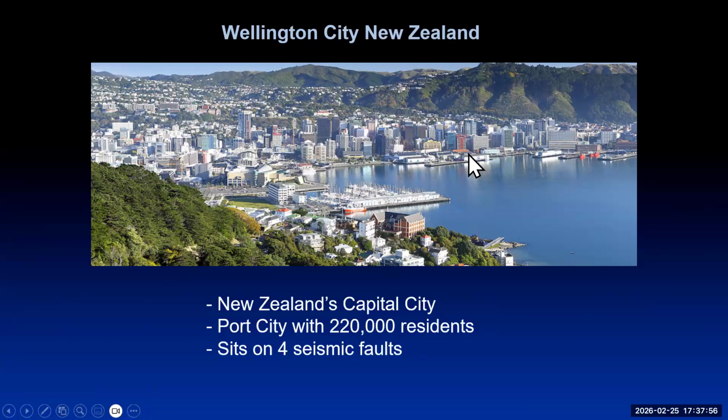What had happened was the Kaikoura earthquake actually happened about 100 miles away. And it was very violent, the second biggest earthquake in New Zealand's history. But it happened in the middle of nowhere. But that wave came up and it propagated. There's actually a fascinating time history on how that wave propagated and what happens as waves propagate like that. The high frequency content gets filtered out and you end up with low frequency waves. So when it hit Wellington, it was about like a 0.1 or 0.2 G, relatively low, but it was at